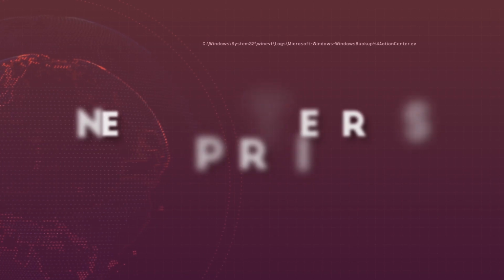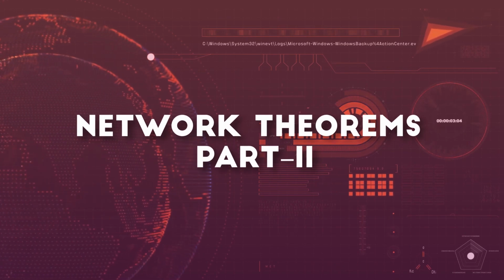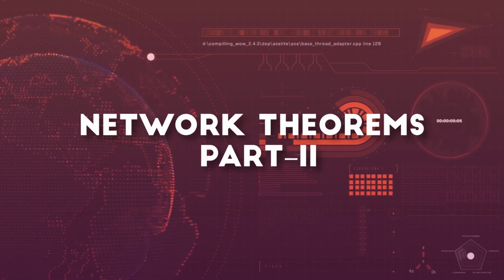Welcome you all again. In the previous session we were discussing the network theorems, and in that session we discussed Thevenin's theorem and the superposition theorem. The superposition theorem states that if there are two or more sources, then the response in any particular branch is equal to the algebraic sum of the responses when one source is considered at a time and the remaining sources are replaced by their internal resistance.